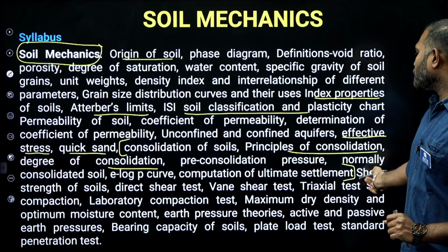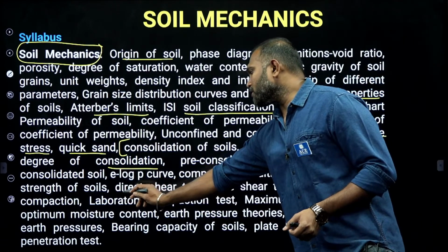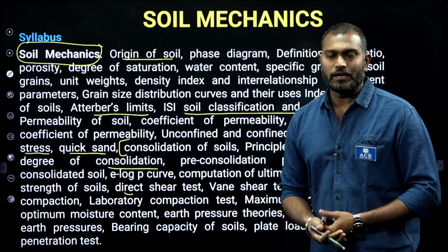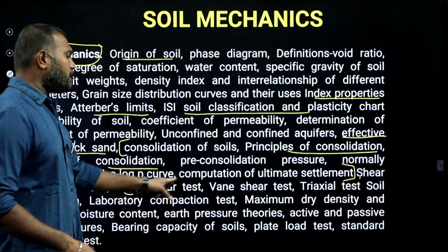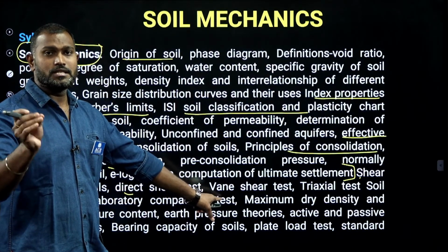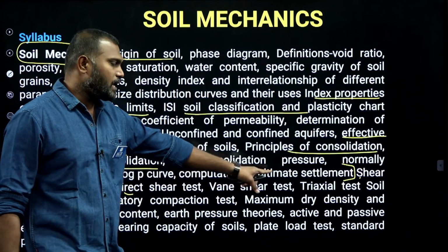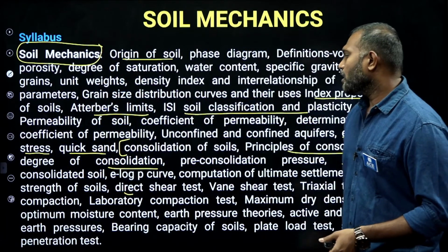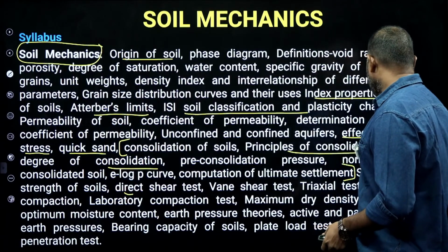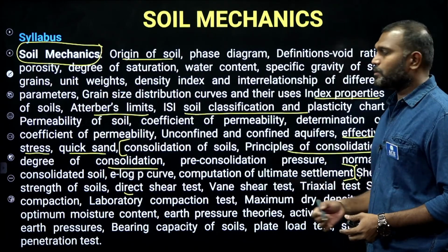And then we discussed the shear strength of soils. In shear strength, we discussed different tests to determine the shear strength: the direct shear test and then the vane shear test. The vane shear test is the one that we do in the field. The triaxial test is the most commonly used lab test to determine the shear strength. So from here to here, we discussed shear strength.